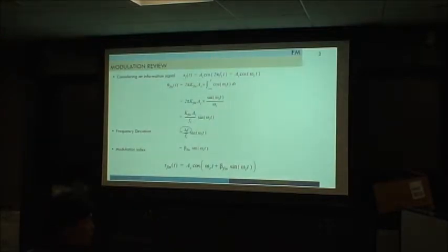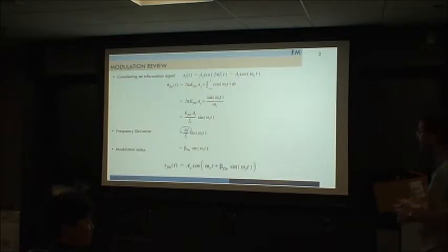what FM does is something like this. Let's say if you have a signal here, okay, so for example, when the frequency goes up, this will be something like this. When the frequency goes down, it will be something like this, and then again this, and so on. Okay, all with the same amplitude, because it's not amplitude modulation, it's frequency modulation. Okay, that is what I am talking about.